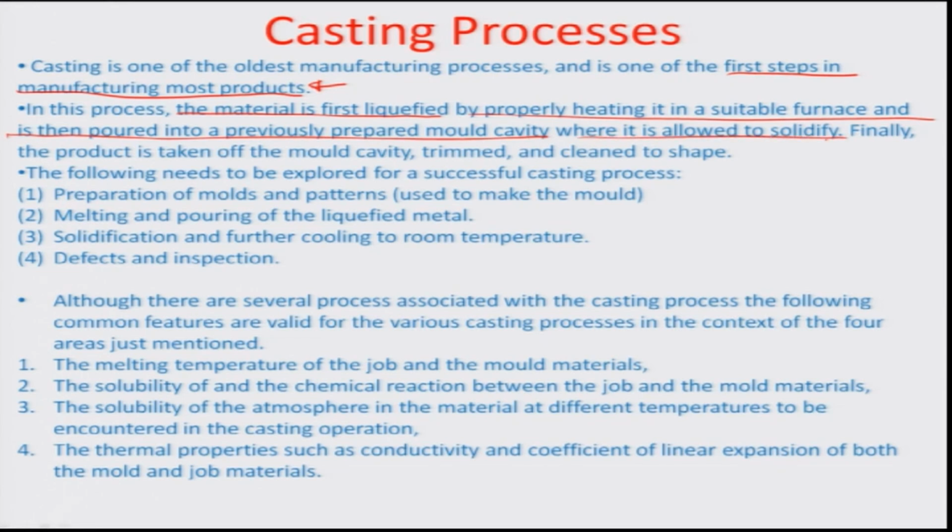So therefore, the important aspect is that the liquid metal is first formulated, and there is a question of liquid metal vis-a-vis liquid alloying, which happens because of the dissolution of a second phase in that, and then it is heated in a suitable furnace, which imposes its own effects by the mode of heating. So for example, if the furnace is induction based, then the heating is completely homogeneous throughout the material, but if a furnace is something where there is a wall based heating, or the heating happens through the walls, there are always going to be temperature gradients.